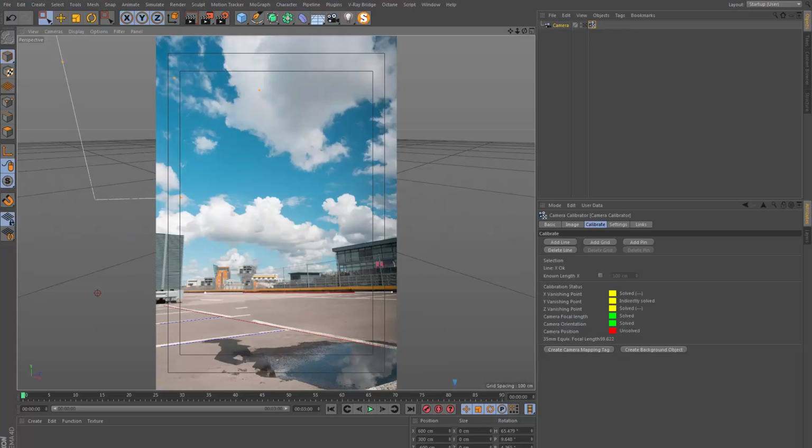So what I can try and do here is move these lines around and try to get closer to that number. So as I move this around, you can see that it does make a difference to this number right here, and it seems moving this line made the biggest difference. So we're down to 43 mil, which is still just too high. So I can try and make this as small as possible, this number right here.